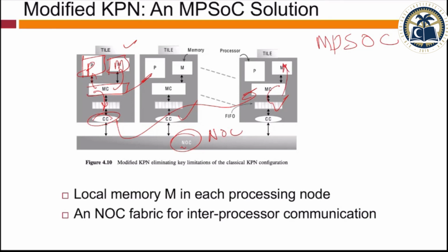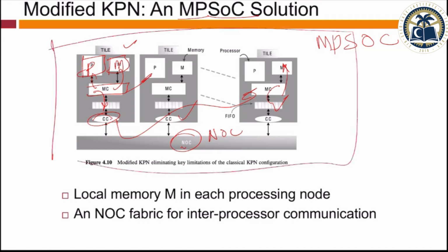You put a network on chip, there are routers, there are switches. This acts like a switch which gets the data and pushes it, a small router which will figure out whether it has to be sent to the right or to the left, but it will ultimately reach this FIFO, which will use its memory controller to make a copy of the data into the memory.